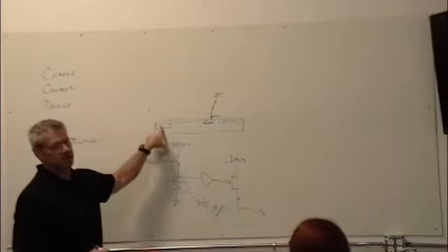Now I come here, and I put a field here, and I put a field here. All these electrons run over here, and I close this one off. And now this thing's already integrated in the next frame. Mm-hmm. And the collection area is blocked. I have a smaller collection area, but now I can read out and integrate at the same time. So as soon as I say, take that picture, I'm already taking the next one while I'm reading this one out. Mm-hmm. So there's no gaps between frames. Really fancy little thing you can do there.